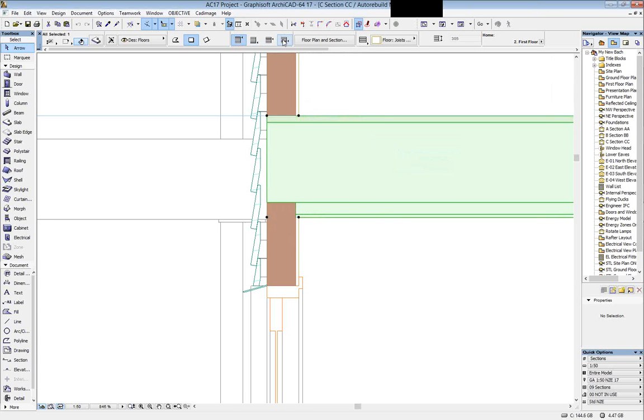Now, this could be quite good. Say, for example, you're doing a multi-story project, concrete floors. Set the reference plane to the top of your structural level. Set that structural level to your structure level in your project. The engineer comes back and tells us what topping thickness it should be. Just go back into your composite, upgrade the topping thickness from whatever it was to whatever it is, and it all changes without your structural levels changing. There's definitely other ways we can use that with slabs.